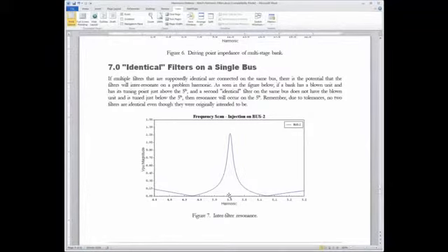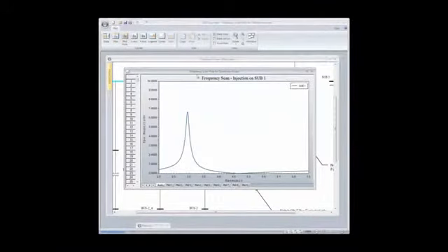The other thing that you can see and discern if you run a few simulations is it causes a resonant condition between the two filters, and their RMS amps double or quadruple. And this is exactly what we saw. I saw a cast in concrete current limiting reactor, which was the reactor for the filter, that was almost red hot. It was really cooking. So if I go back to EasyPower, I have a case that I can load to show us.